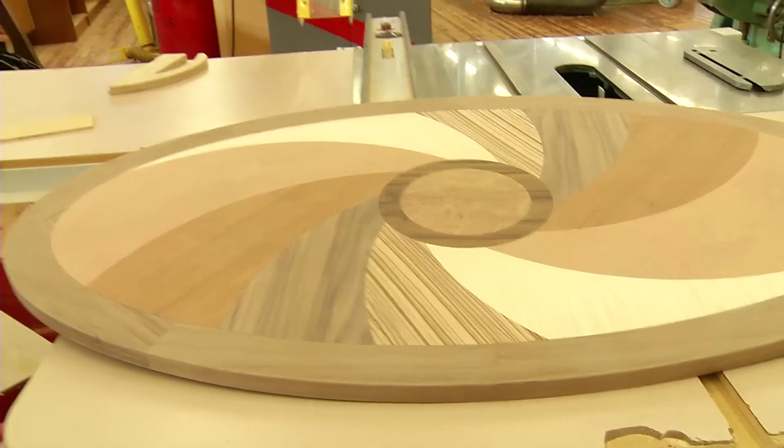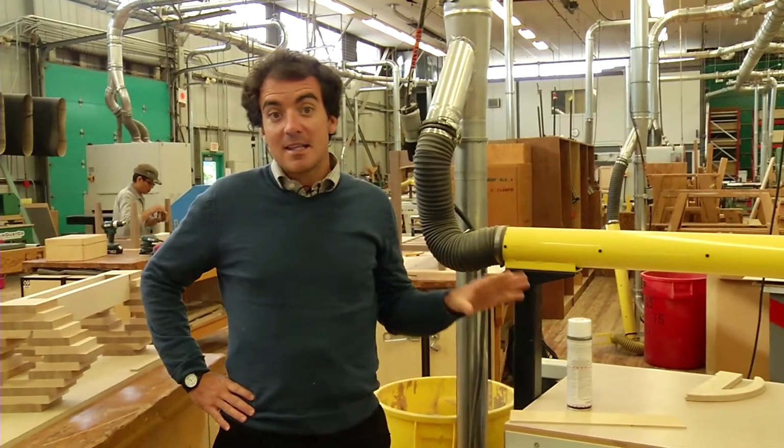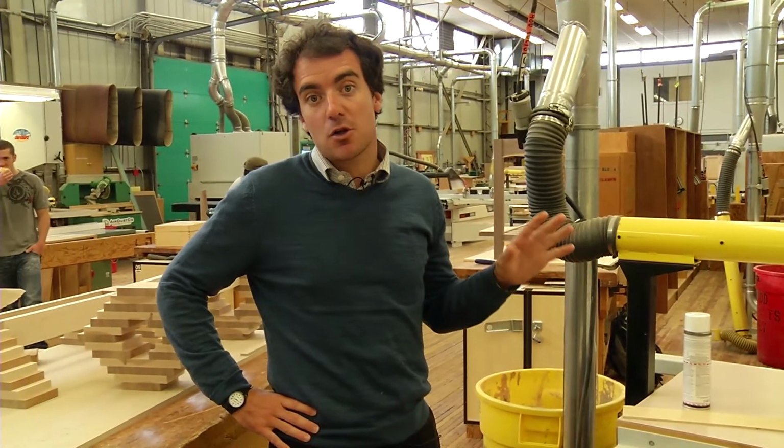So that allowed us to reduce the size of the fan and reduce the size of the motors so that our overall capacity is for plus or minus 64 workstations. We wanted to have a safety factor, so we went up for a bit more than 64 workstations. But downsizing the size of the motor means that we're using less energy when it's operating. This is a very good example of how you can conserve energy.